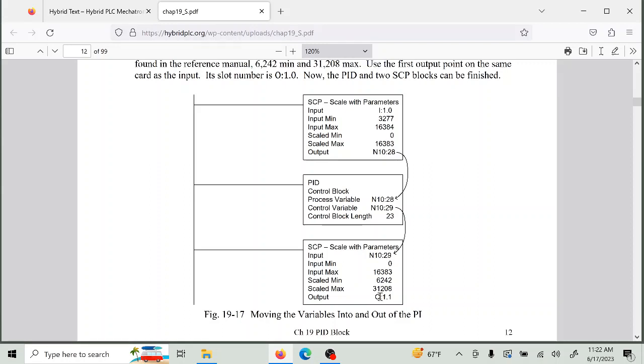They have to update frequently, because if you don't have a quick update and you're taking variables that are not fresh, that are maybe 20, 30 milliseconds old, your calculations are based on information that was 20, 30, maybe 50 milliseconds delayed, and they're not as good as if they were information that you just had recently, like within the last couple of milliseconds. You want fresh and updated information, and that's why it's important to configure these cards correctly.